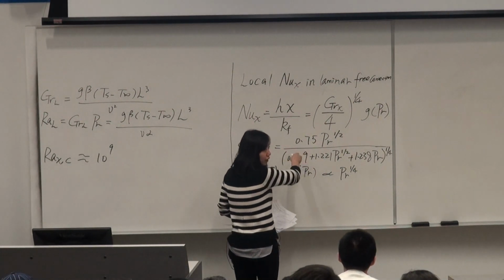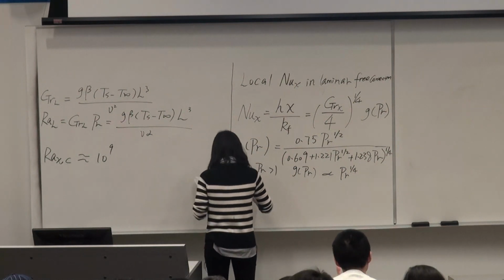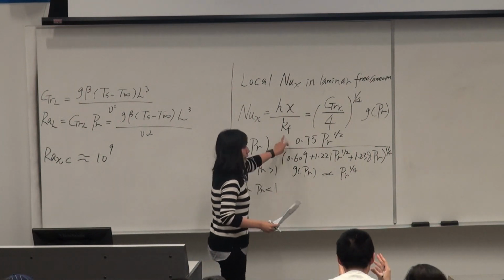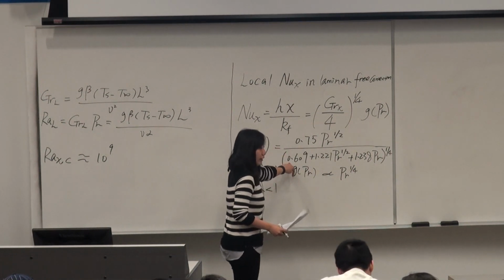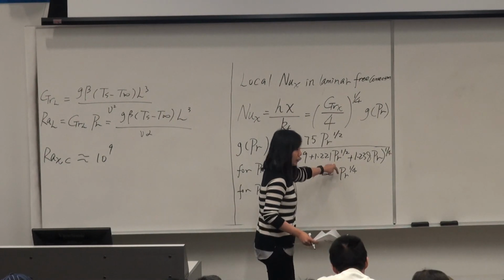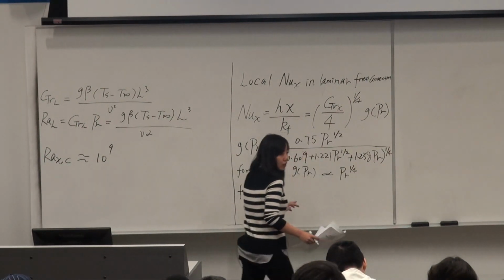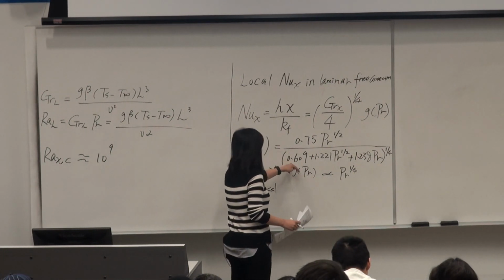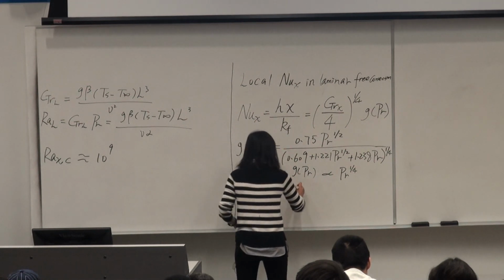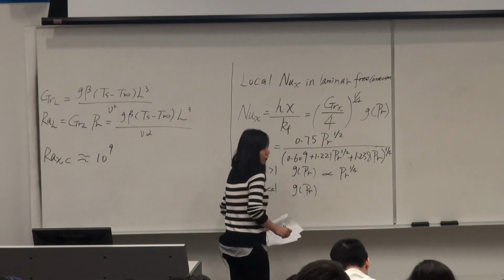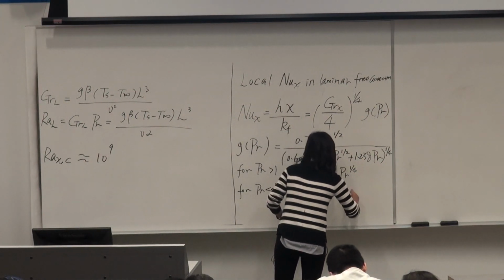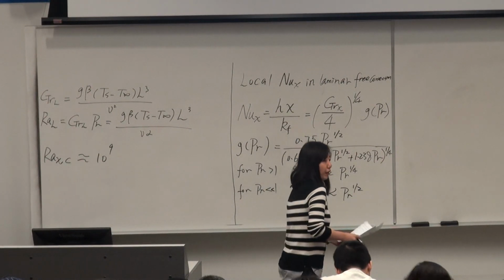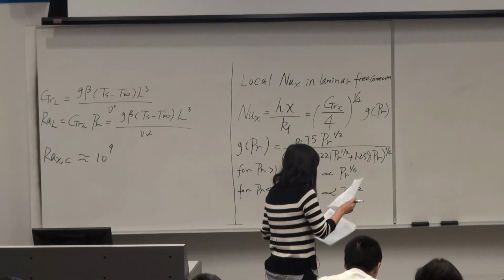We don't need to remember those super complex interpolations. But for Prandtl number smaller than 1, it is the same as above, but now you have a 0.6 here, and the Prandtl number squared, and the Prandtl number itself below. Now this constant 0.6 dominates, giving a constant over a constant. For Prandtl number much smaller than 1, your dependence on Prandtl is proportional to the numerator itself, to the square root of the Prandtl number. And that's it.